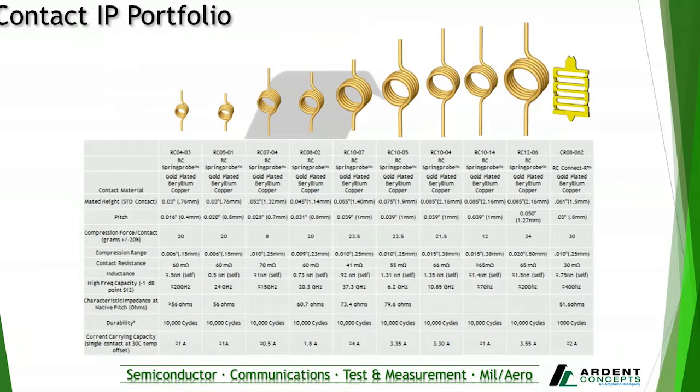So the culmination of these unique single element contact technologies allows for a very short compressed contact. And the short electrical length allows for superb signal integrity and performance. Along with having a very short electrical length, the shorting method of the contact compression technology provides a contact with low self-inductance. And this is balanced by the dielectric values of the housings that these wire forms are inserted into to produce an electrical interconnect with a controlled impedance of 50 ohms.